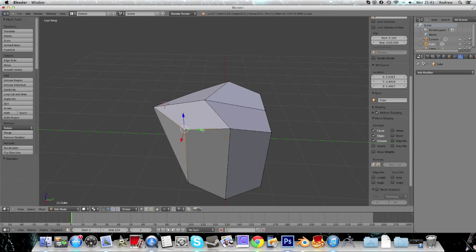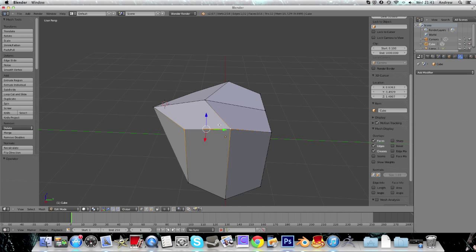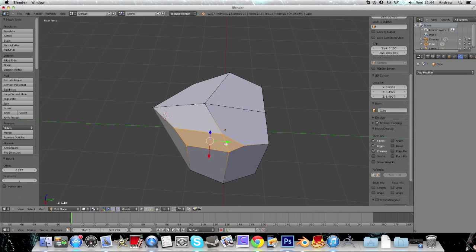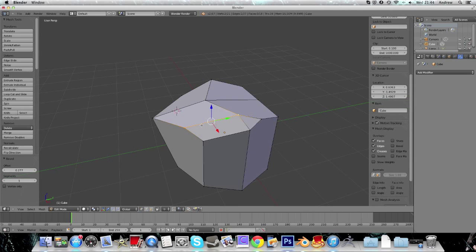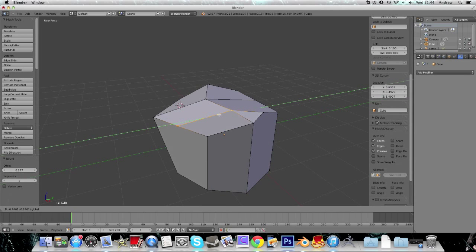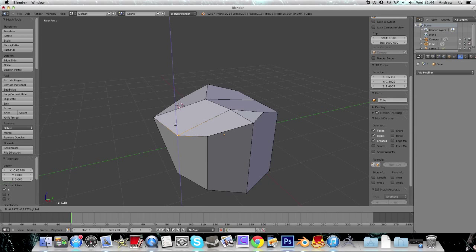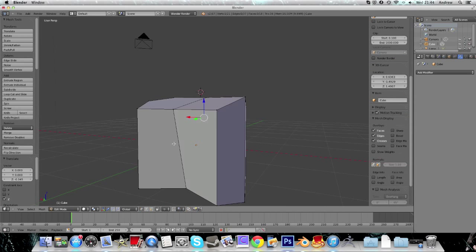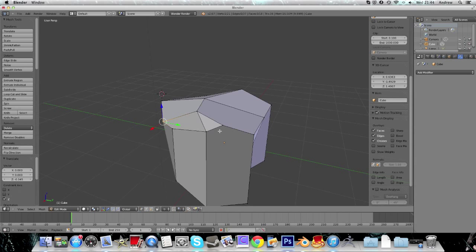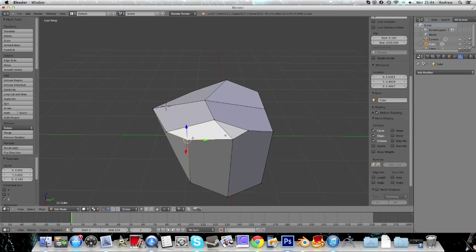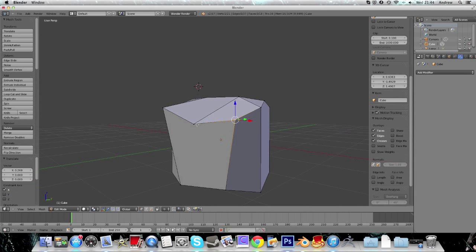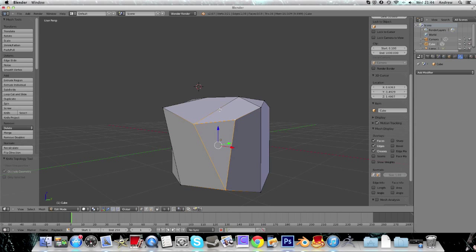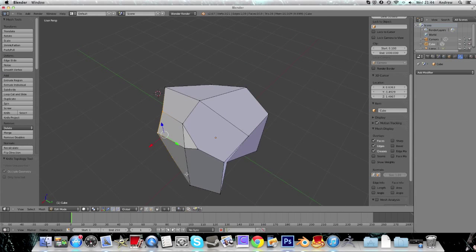The main use, which makes it so good and really handy, is that when we're beveling, so I'm going to bevel this edge here again, we're adding in more vertices to our shape. So we can make some areas more realistic, or give them more detail and move it into the shape that we want, without adding an entire ring loop across the whole of our geometry, which could mess it up, or we would have too much if we did that the whole time. That's really useful. It also makes some extra mesh, so we can use the cut tool, which we looked at before, with K to get rid of some mesh if we didn't want it for whatever reason.